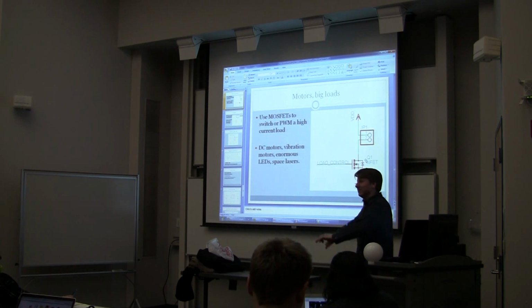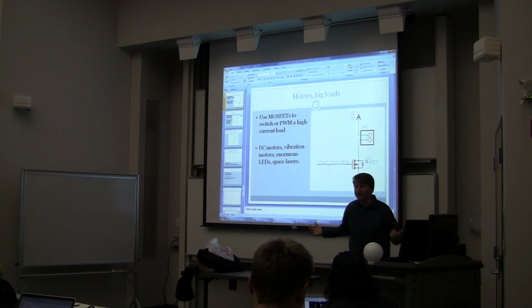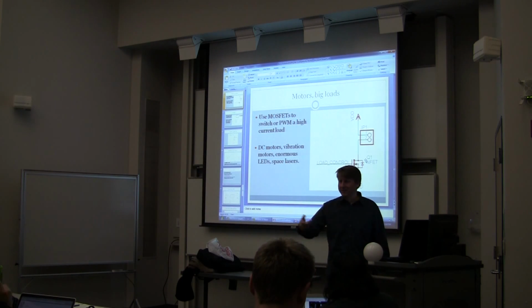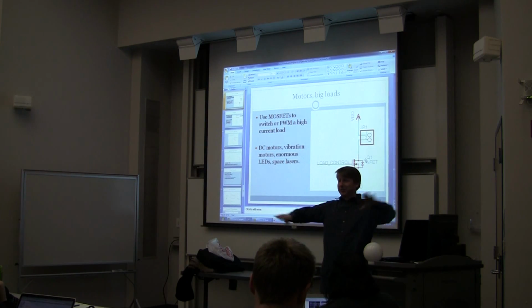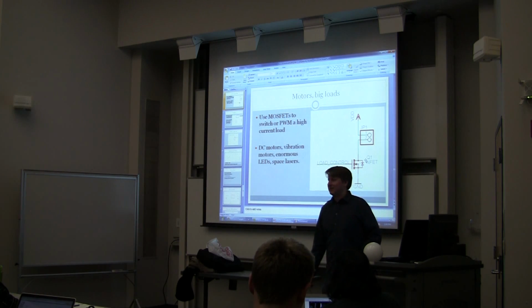If you wanted to do giant 5-foot long strips of LED light strips, you'd give it 12 volts, and then you just use 3 MOSFETs on your board, turn them on. It would work the same as the tricolor LED on your board. It would just light up the whole room. So I think that's it. People have questions? Otherwise, hopefully this helps for Gadget 1.